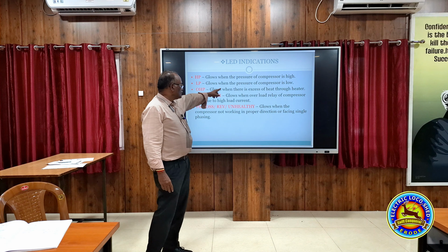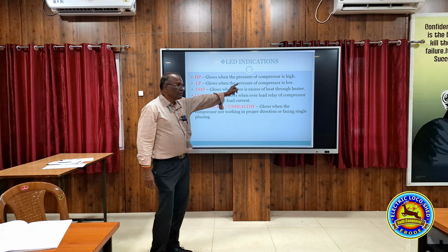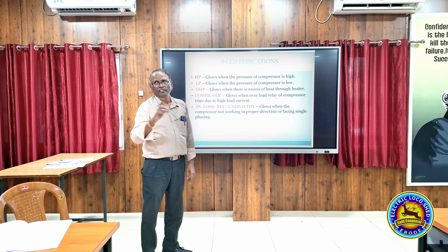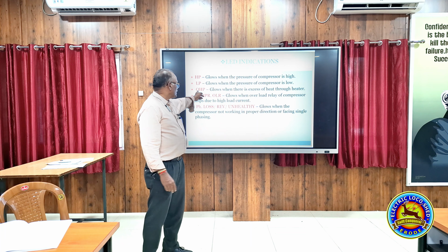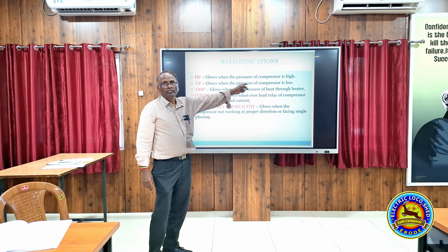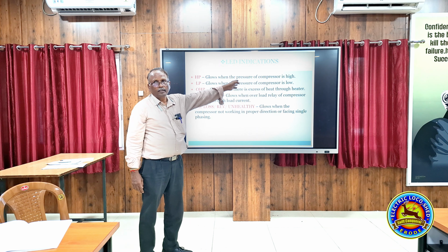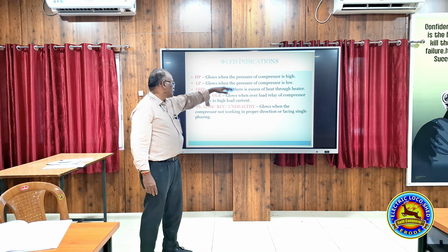Low pressure glows when the refrigerant pressure is low. Our standard pressure is 60 to 70 psi. If it reaches below 30 or 35 psi, this low pressure indication will come and the cooling will be less, and then the compressor will trip.